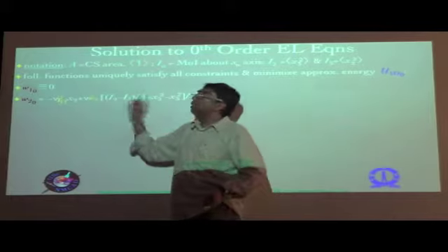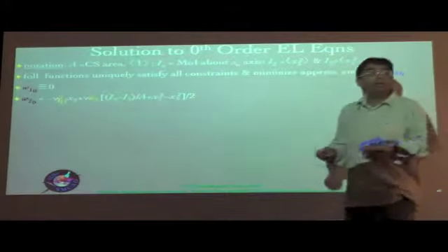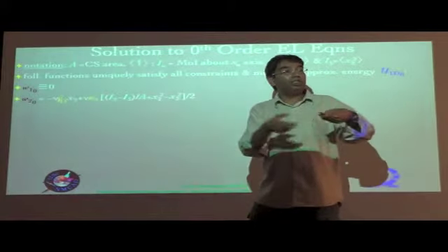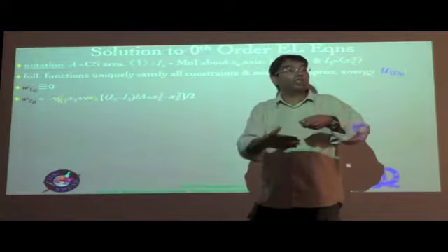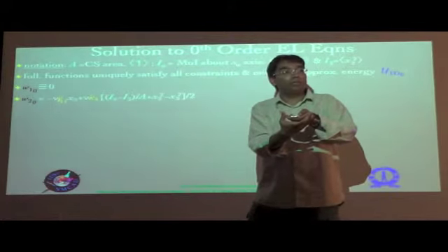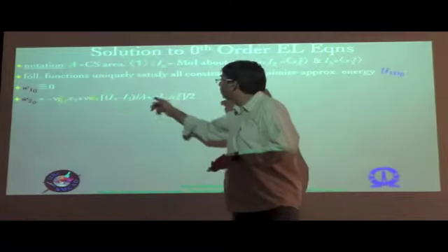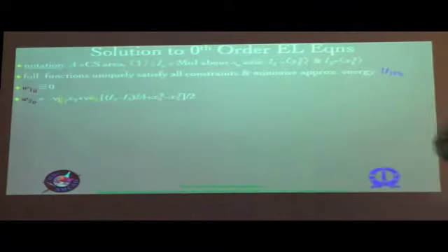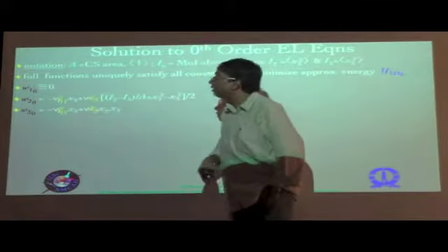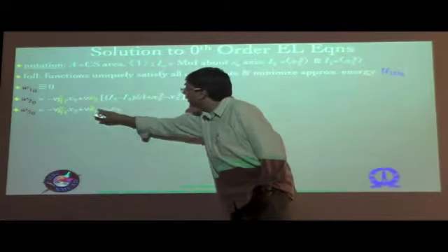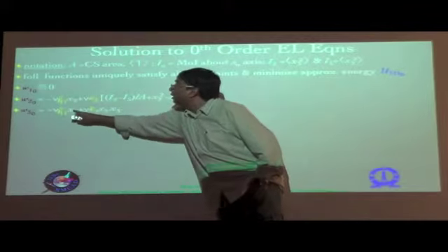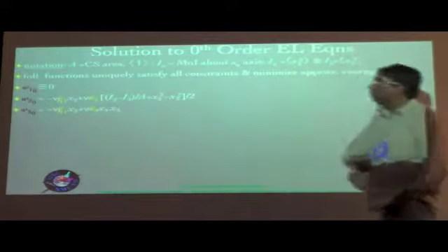Similarly, you can see how the kappa 3 bar contributes as well, because kappa 3 bar contributes bending, which will involve both extension and compression in different parts of the cross section. Where there is extension, when you have a positive Poisson's ratio, in the other direction you will have compression, and vice versa. And that's why you see terms involving x2 squared, x3 squared, etc. over here. Similarly, you have a W3 term over here as well. Once again, there is a quadratic contribution because of kappa 3 and a linear contribution of x3 in terms of the gamma 1 bar term.